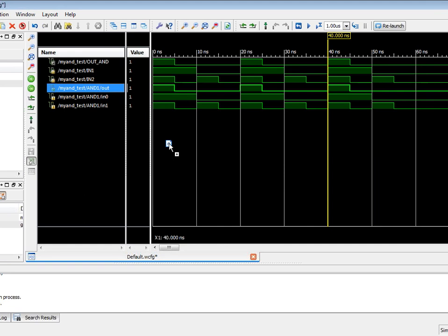So from the next lecture onwards, we would do only practice. There are a couple more lectures left. I've already given you a few tasks to create a few combinational circuits and a couple of sequential circuits. So you can create the design as well as the test bench file for each circuit. Then you can create a separate project like we did for each circuit, run the simulation, generate the timing diagram, and analyze the timing.